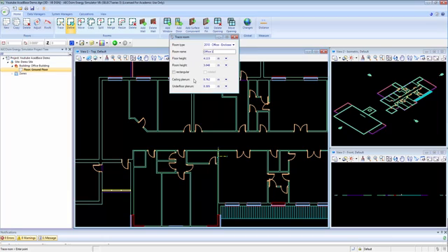Floor height, room height, and the ceiling and underfloor plenum space are there, so you can set all of these. If I just change this to 4 meters, you'll see it adjusted those as well. For room height, I'm going to set this to 2.4 for the sake of argument, and see how it adjusts the plenums.